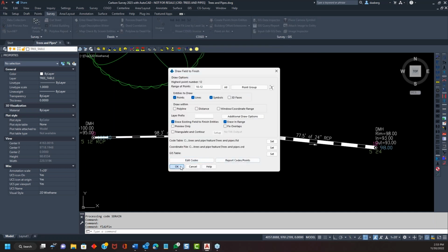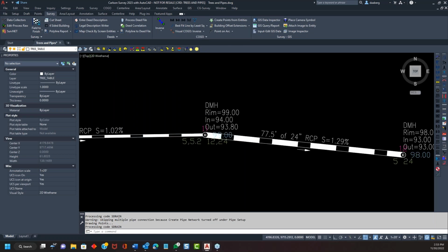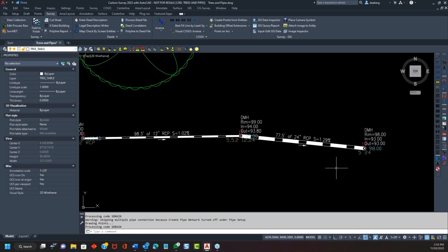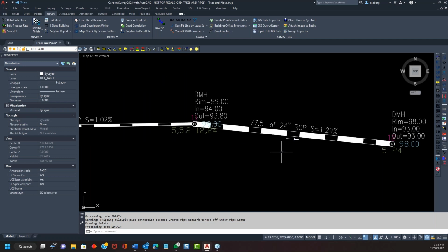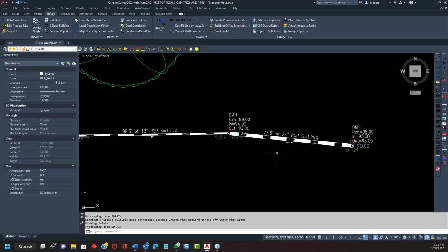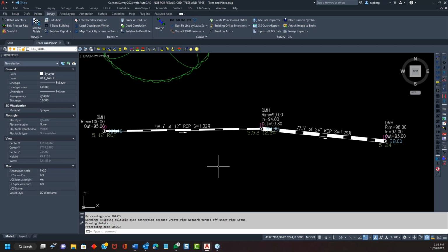So now I can add the slope to the plan as well. So it beats calculating the slope. That little arrow is a choice. It can go off to the side or it can go right on the pipe, or you don't have to have that if you don't want it. If you're doing pipe, I usually use this for as-built surveys. But again, some clients require that the pipes be drawn because they're looking for collision checks visually, that they're drawn at the actual width. So this is a nice option to have that done in there.